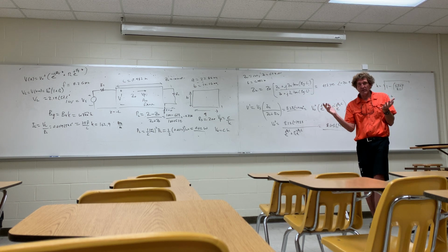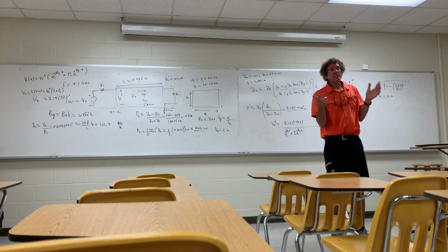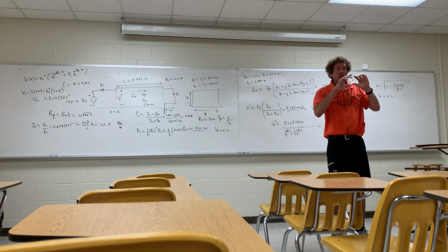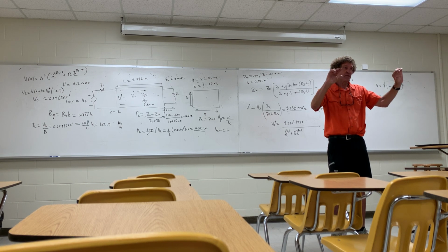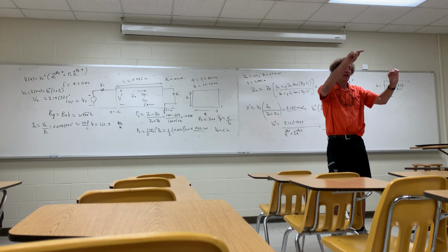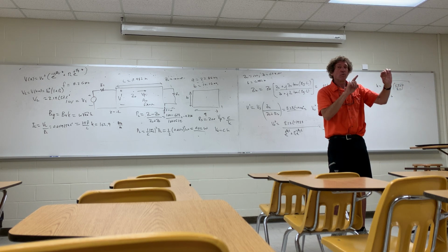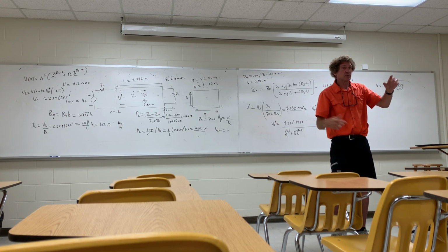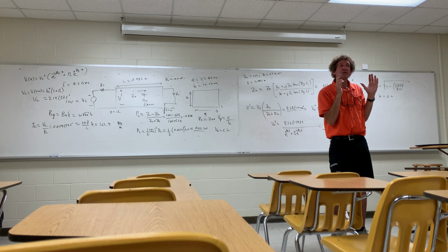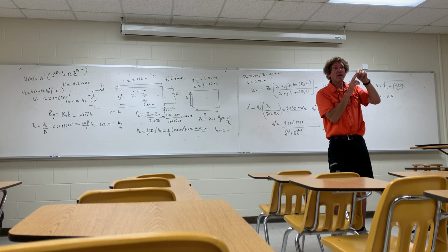Has anybody ever had slab waveguides or waveguides in physics? What it amounts to is this. When you have a slab of dielectric material that has, assume no loss, but it's got an epsilon relative greater than the media around it. So it might have an epsilon relative of 2 or 3, and then say an epsilon relative of 1. What happens is the waves ricochet back and forth, just like they do in a perfect conducting rectangular waveguide. But the problem is this. Some of that wave actually penetrates into the second media, and it decays exponentially.